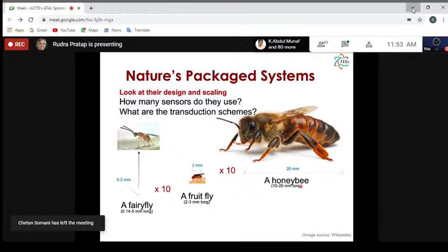And now if I deposit polysilicon on top, then polysilicon will be deposited as a layer on top, as well as in this groove that I made by removing the oxide from there. Now, if I remove the sacrificial oxide, then what I have is a free polysilicon beam sitting here, right? Which is anchored in this portion to the substrate. And that's how you get a cantilever beam.